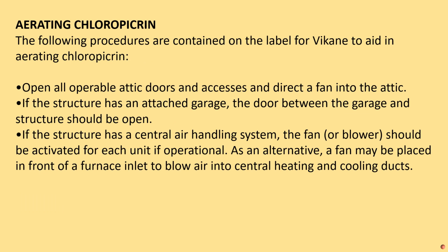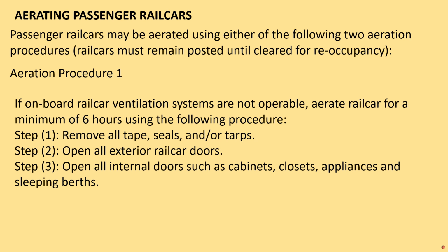Aerating chloropicrin. The following procedures are contained on the label for Vikane to aid in aerating chloropicrin. Open all operable attic doors and accesses and direct a fan into the attic. If the structure has an attached garage, the door between the garage and the structure should be open. If the structure has a central air handling system, the fan or blower should be activated for each unit if operational. As an alternative, a fan may be placed in front of a furnace inlet to blow air into central heating and cooling ducts.